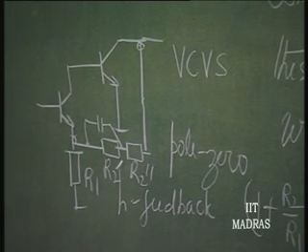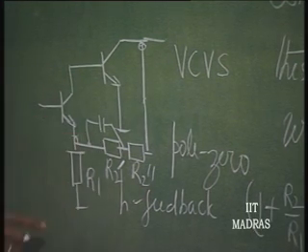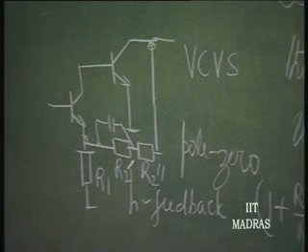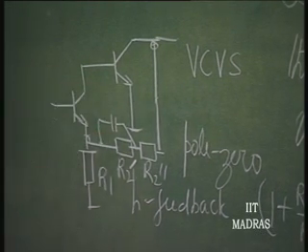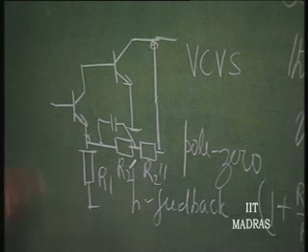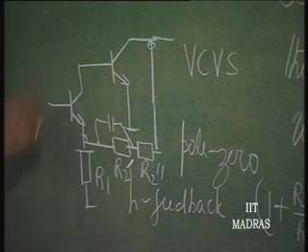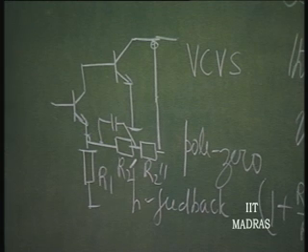Most of the time it is very difficult to find out exactly where these poles are located, and therefore, you can in any case split this and put a capacitor, keep varying it until it stops oscillating, and then provide a little bit more, so that there is enough margin, so that at all conditions it is not going to oscillate. And therefore, this kind of compensation results in the widest bandwidth for the amplifier, which is a voltage controlled